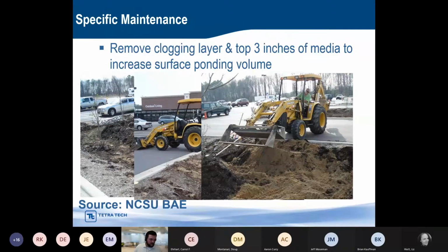So how about river rock instead of mulch in areas that might have swiftly moving stormwater? I think rock can be a replacement for mulch. I've also seen it in areas that have a lot of intense sunlight, which is generally something we see more out in the arid southwest, where mulch tends to degrade pretty quickly. But rock can be a substitute. So if your water's, it's generally about a foot per second. If the velocity of your flow is more than a foot per second, you're going to need something more solid than mulch. So turf grass or bringing in sod can also be a good alternative.